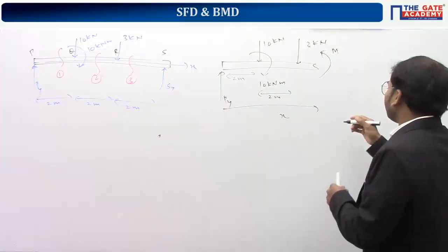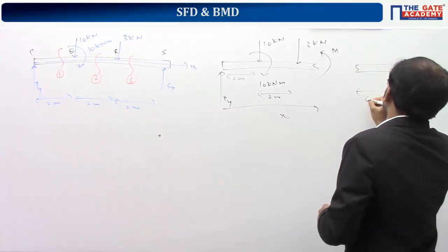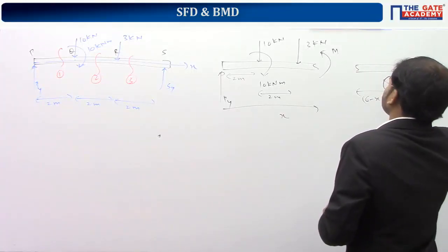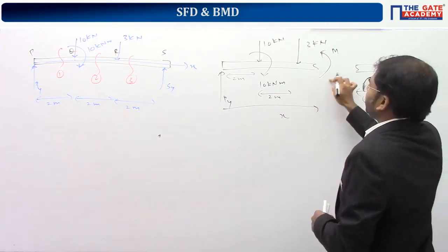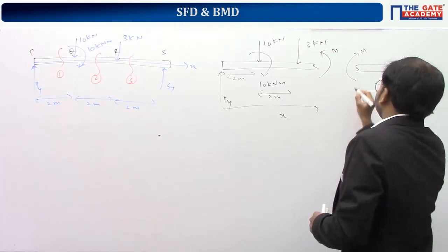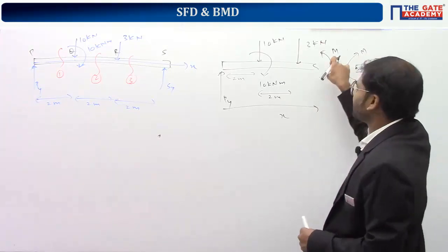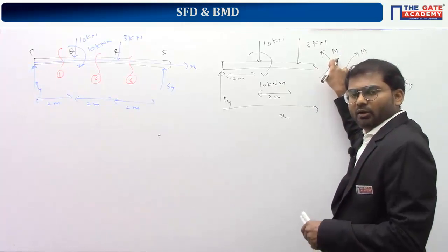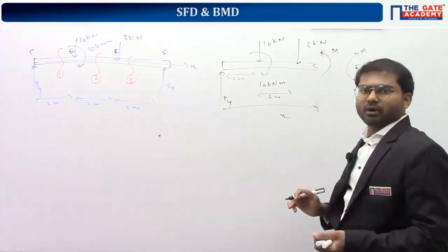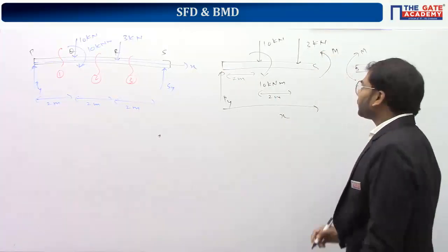Instead, if you take the right part of the cut, this becomes a total of 6 minus x. Here there's a force of Sy. Here anti-clockwise means here it should be clockwise. If you take moments about this point, you'll get the value of m. The point x equal to 4 is included in the range.